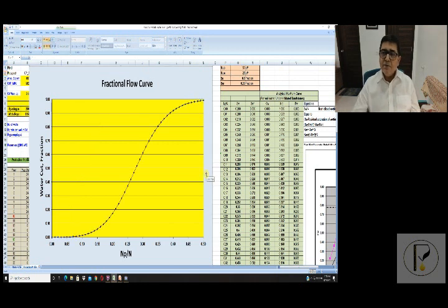So the first attempt, what some people want to attempt, is to increase the viscosity to 25 centipoise by adding polymers. Okay, so by adding polymers, you see the curve has shifted to the right. So here, what is happening? The mobility contrast has gone down now. It's close to 2.